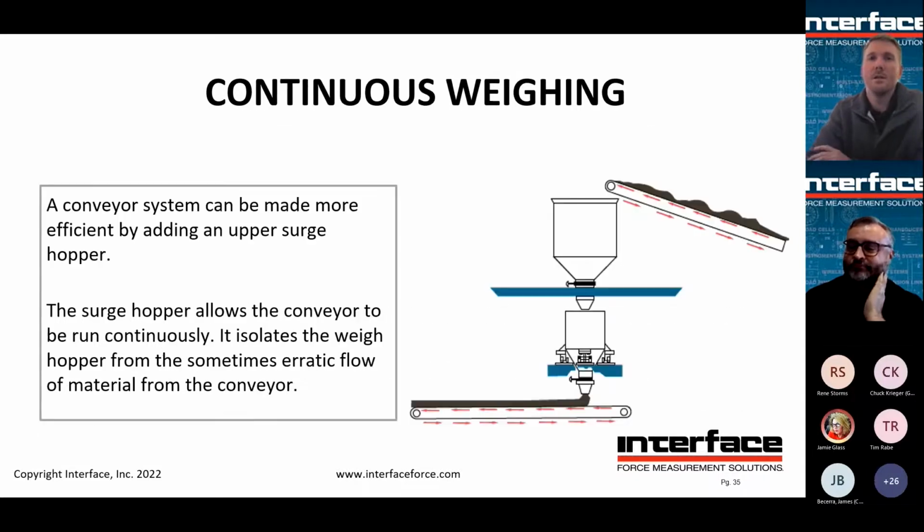Next slide. A couple of these more just some ideas. So you can't really fill and discharge at the same time. This is also a way to do with belt scales. Belt scales we don't really touch on in this presentation, but I'll mention them briefly. They are a cost-effective way, but in my experience, sometimes a finicky solution to measure throughput. They offer rate in tons per hour and will give you accumulated total, but there are many variables on belt scales such as tension, conveyor angle, speed, material flow consistency.